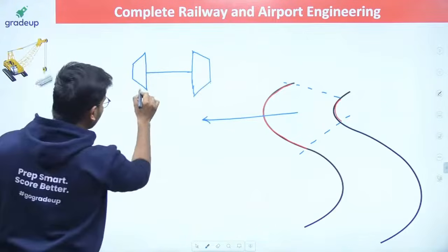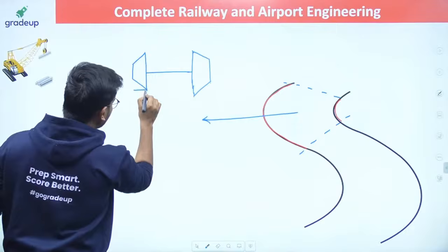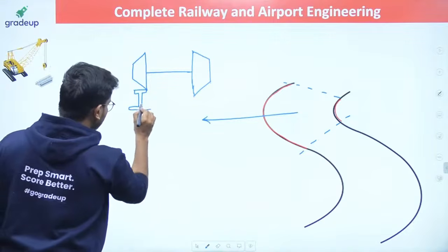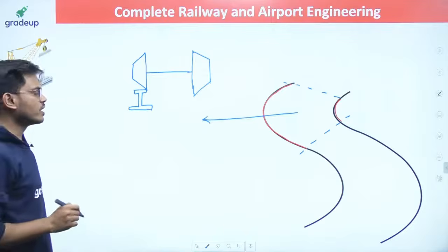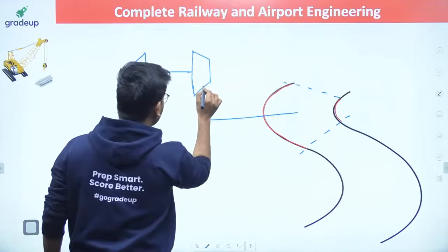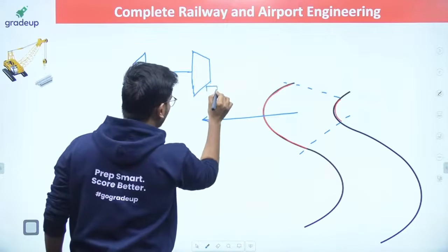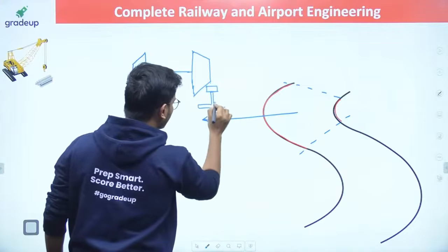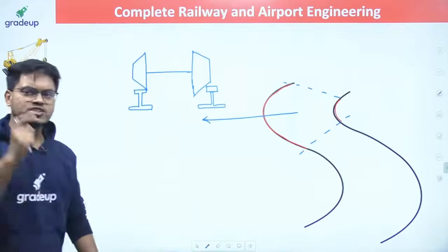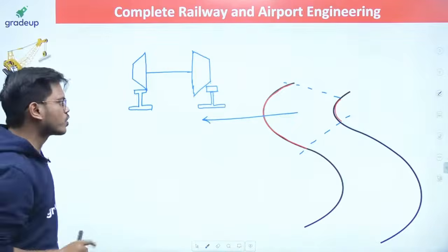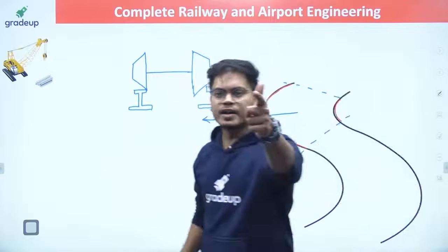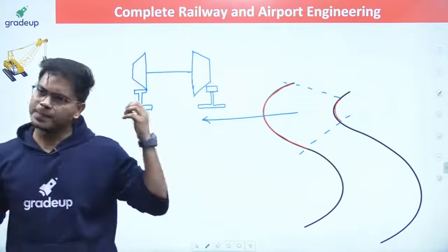The larger diameter will come on the rail, and the smaller diameter here will come on the rail. And I have already told you that the small diameter for one rotation is going to cover less distance and the larger diameter will cover more distance. Agreed or not? With full power, everybody please answer.